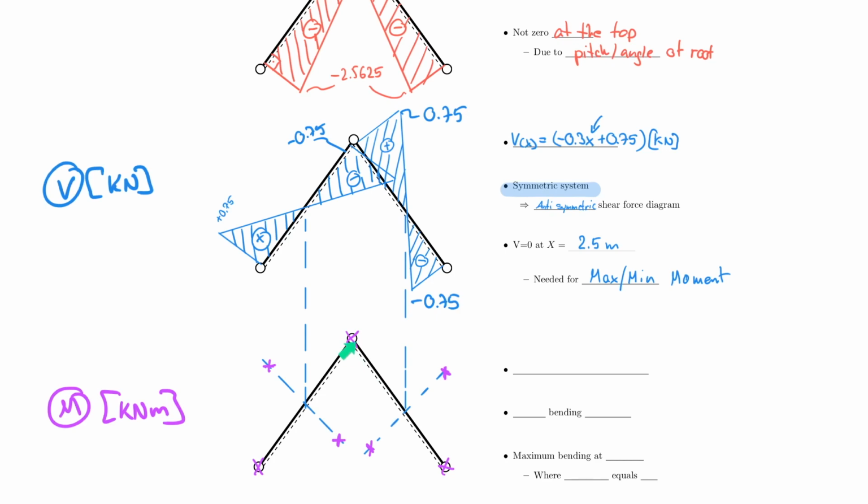Last thing now is positive or negative. So effectively, do I draw my arch this way or this way? And the answer is easy. If you remember, compression on the top, tension on the bottom is a positive moment. That is exactly what we have here, or as we called it in the class, the beam is smiling. So this beam here is literally smiling. It wants to bow down. And because it wants to bow down, the moment is positive.